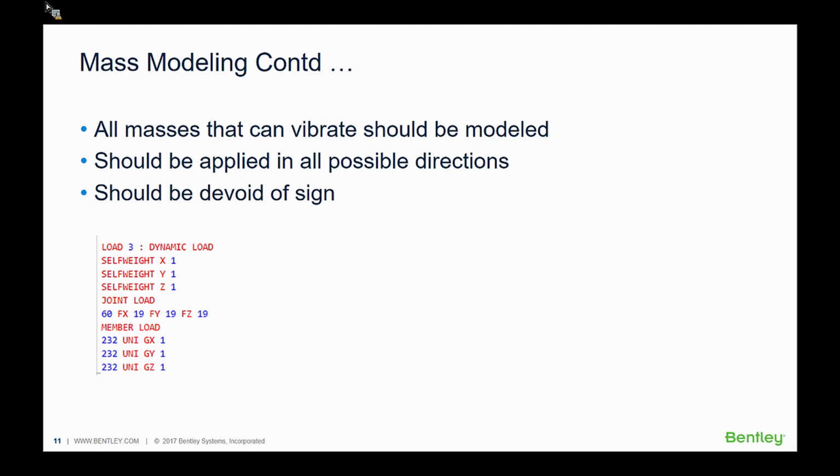The load should also be entered as a positive number, even though it may be acting in the negative y direction, because eventually the software is going to calculate the masses from these loads. And STAAD Pro does an algebraic summation of masses at the various nodes. And so if some are entered as positive numbers and some are entered as negative numbers, these masses may cancel out. So be mindful of that.